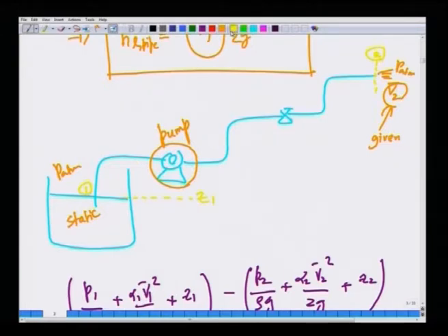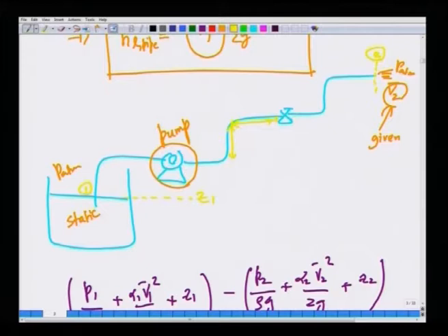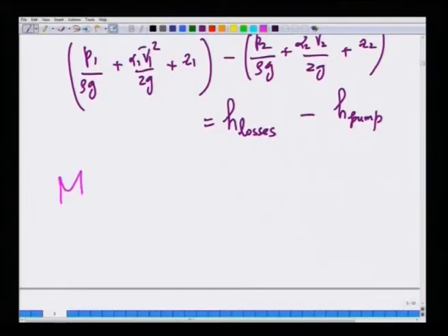Now, there are various segments in which the flow is straight. The flow is through a straight pipe. Here we have to estimate the losses using the friction factor chart. So, whenever there are straight segments of pipes, the losses in those pieces of the pipeline network will have to be calculated from the friction factor chart. Such losses are called traditionally major losses, because they contribute numerically the most to the losses present.